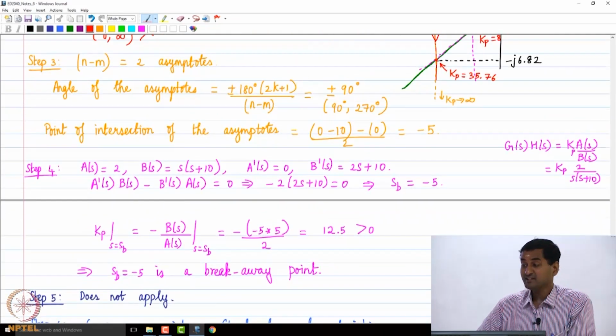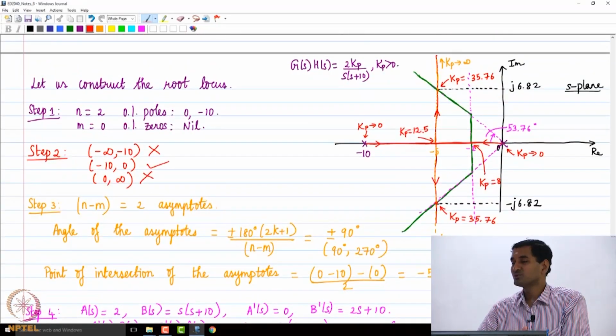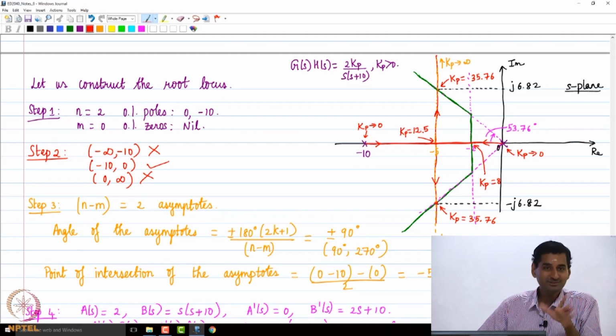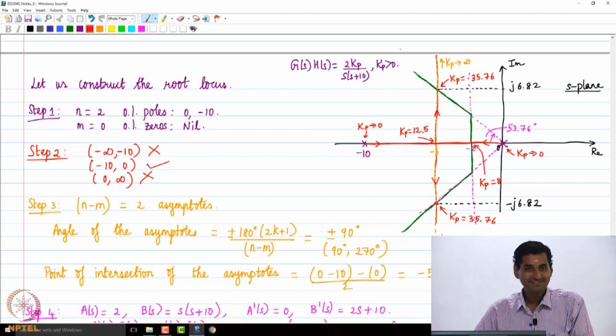And you can immediately see that root locus is a very handy tool to know, because you can have a graphical visualization. If I had asked you how to satisfy these performance conditions without a root locus, it would have been very difficult, more challenging to get these bounds on KP. With root locus, it was quite straightforward and also very intuitive, because we can see the graphical visualization.